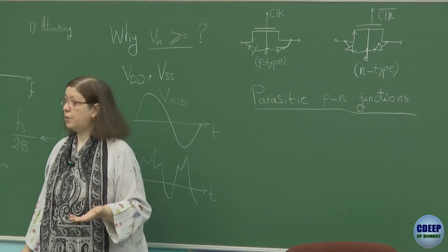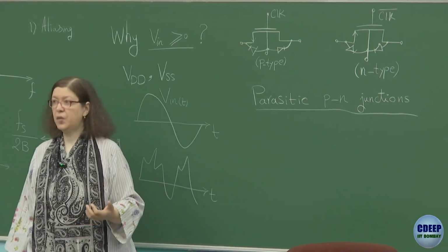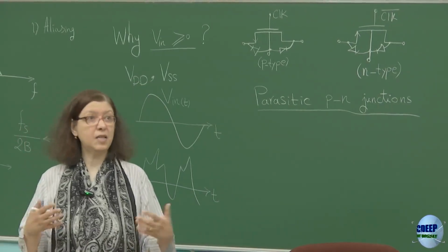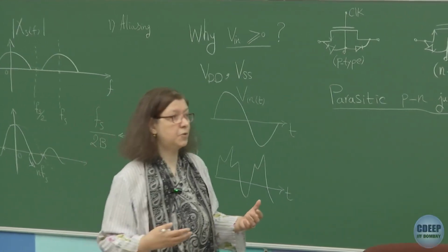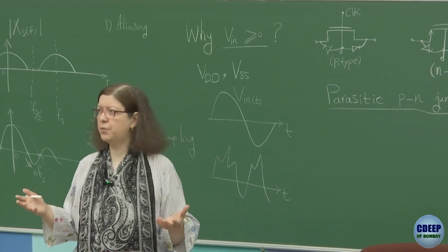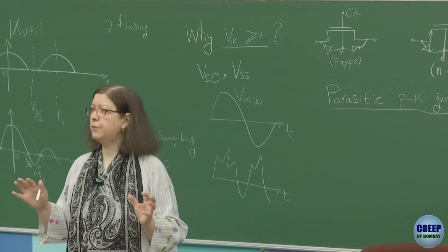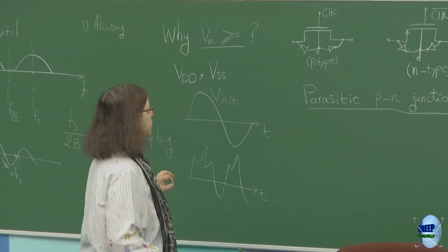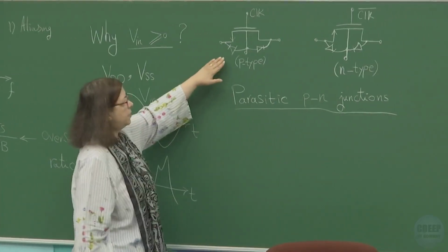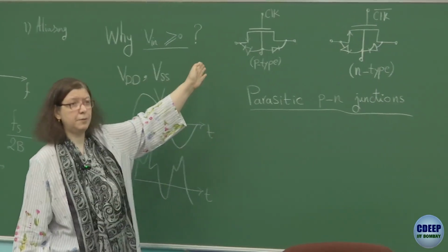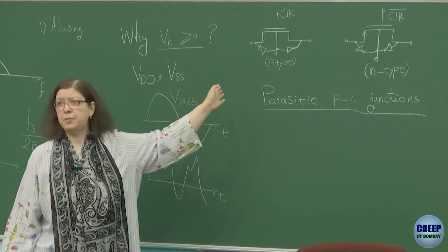Now, to ensure that this is happening, unless a designer has enough experience to deal with the conditions under any value of the input signal, we create a kind of constraint. To make sure that your devices are always in the right condition, unless on purpose you want to turn on this diode, you need to keep them reverse biased.